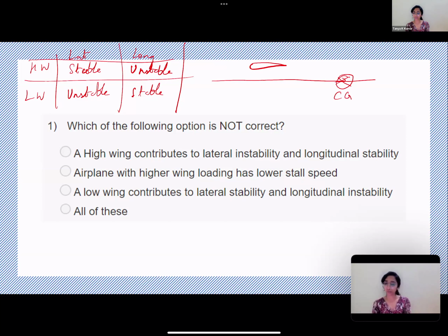So can you try, what are the aerodynamic forces that the wing produces? What are the forces? Lift, drag, and pitching moment. Okay. Just the forces? Okay, fine. Let's just go lift, drag, and let's assume that it is a symmetric airfoil, so you have no pitching moment.